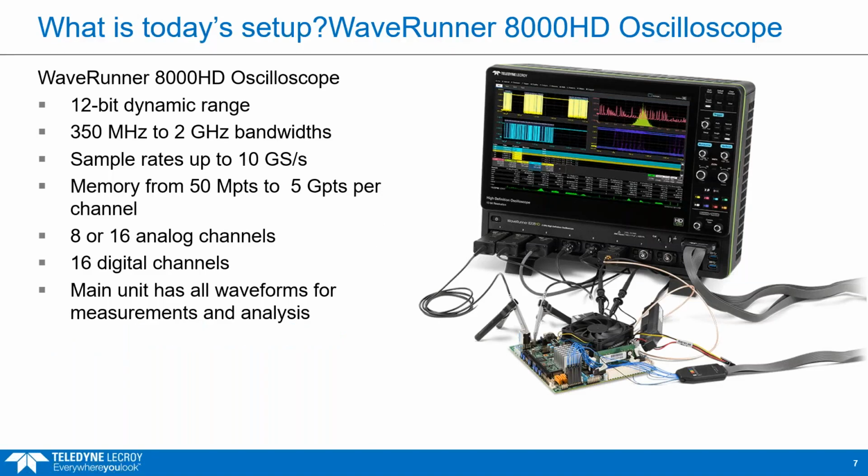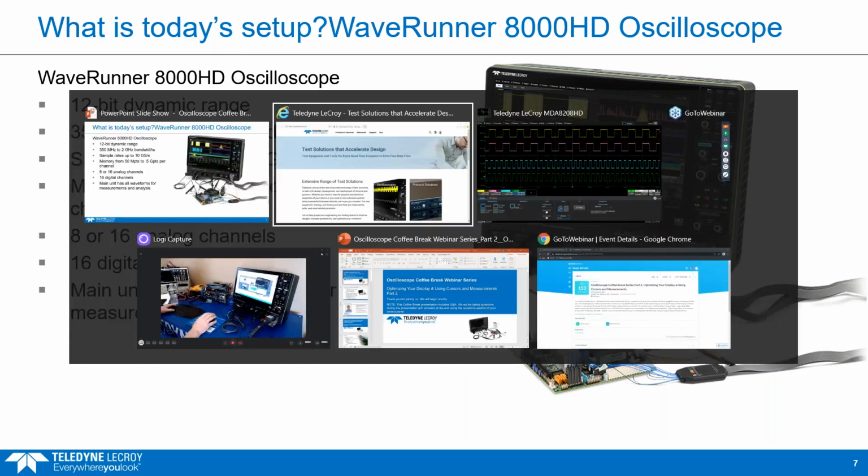What do I have set up? What am I using today? This is a WaveRunner 8000 HD. It's a 2 gig scope that I'm using today, and that's the sample rate. The memory length varies from 50 million to up to 5 gig. You have 8 channels, or put 2 of them together, and then there are 16 digital channels.